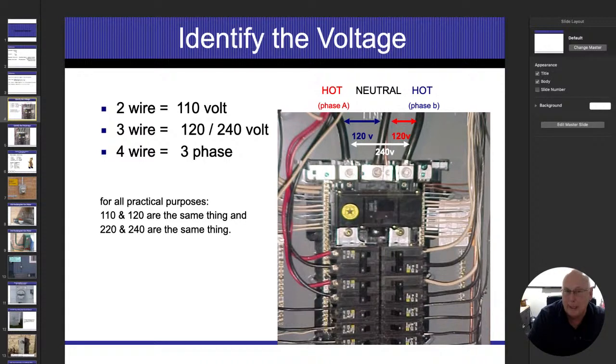And if you remember, I said amps don't disappear. So, off the cuff, I could start thinking, well, shouldn't I be sending 200 amps if they're fully loaded up there? That's not true. They don't disappear, but they do cancel each other out. And that's why we can get by with 2 energized conductors and only 1 neutral. We don't have to have 2 neutrals coming back out of it. In fact, nowadays we do what we call shared neutrals on many circuits inside of a house.